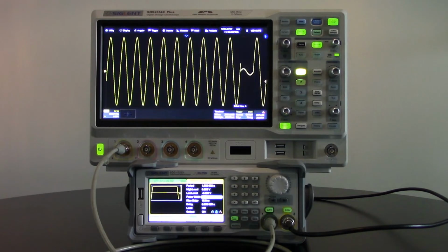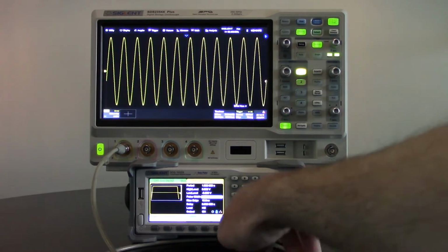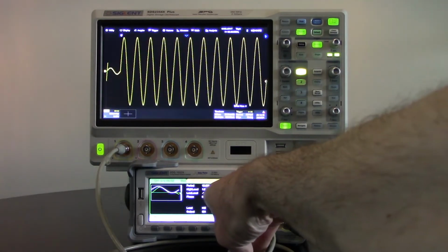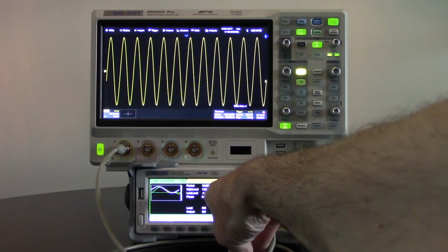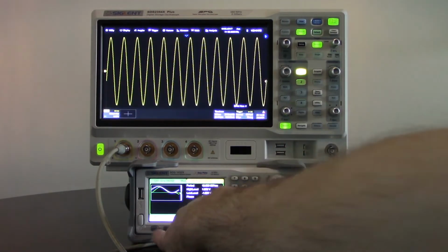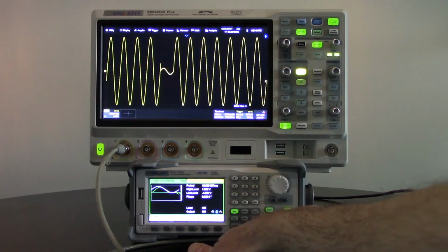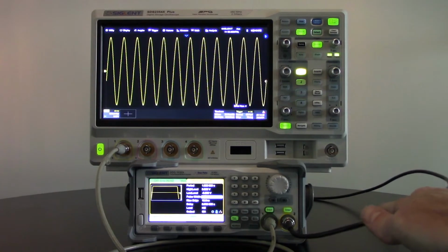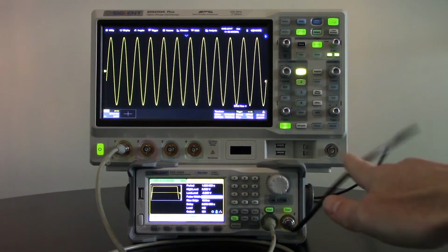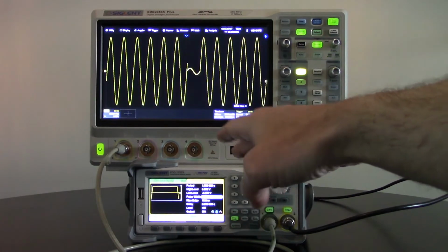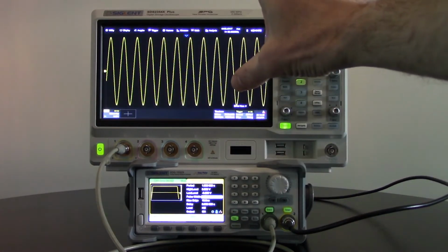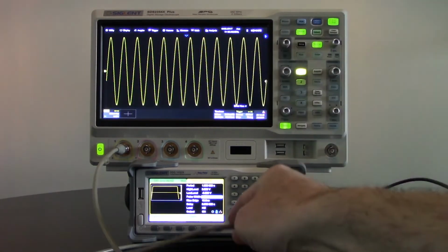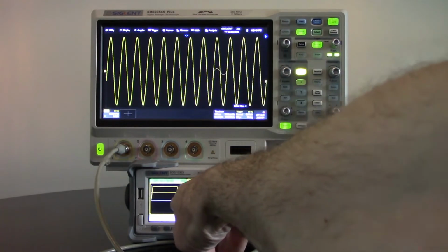So I set up a little experiment here in which I am using one of our function generators. Channel 1 is going to be putting out an amplitude modulated sine wave, so the high and low levels are set here, but I'm at 16.67 milliseconds, so 60 hertz on that sine wave, and then I'm modulating it using channel 2. In this particular case, channel 2 is staying high for a period of time. That means I'm going to get full amplitude out of that AM modulated signal for channel 1. Then I'm going to decrease the amplitude for channel 1 by dropping this voltage value on the pulse.